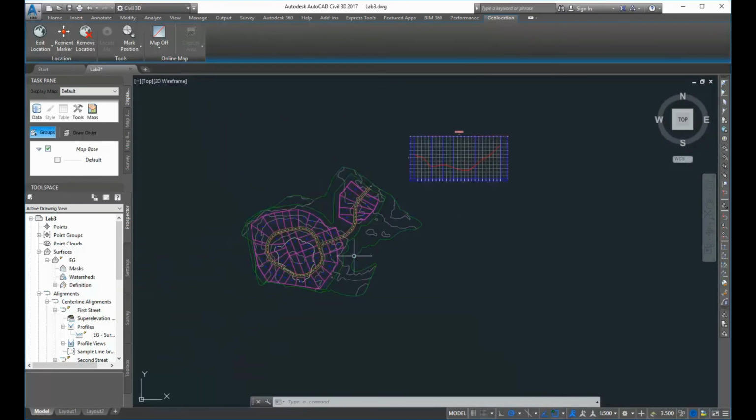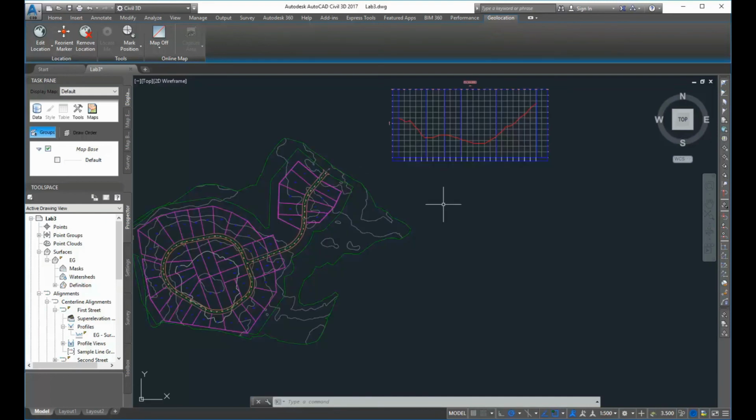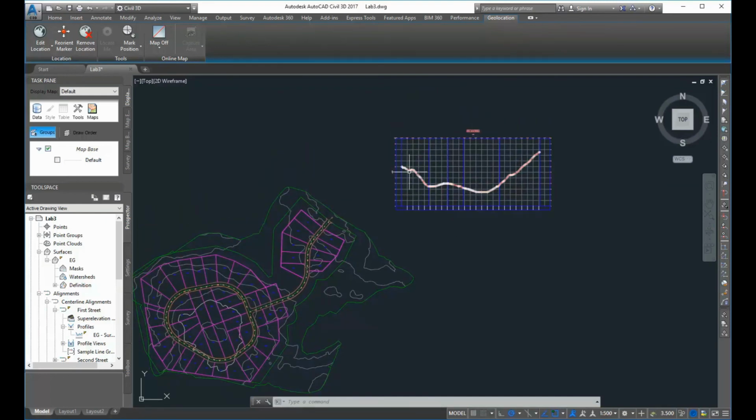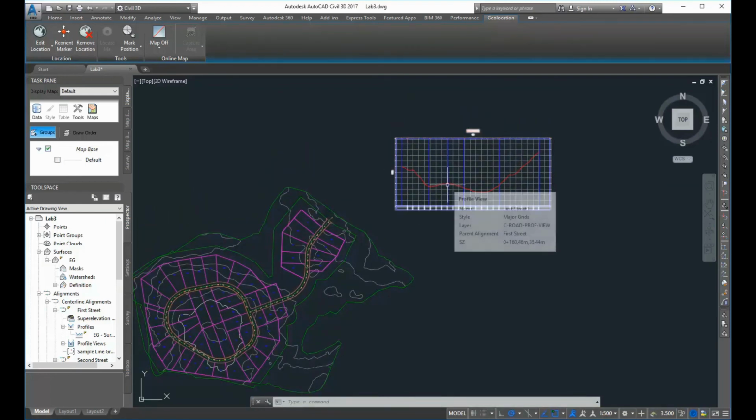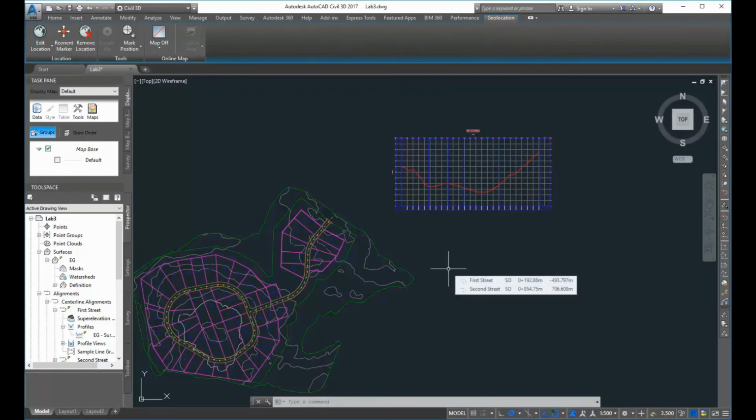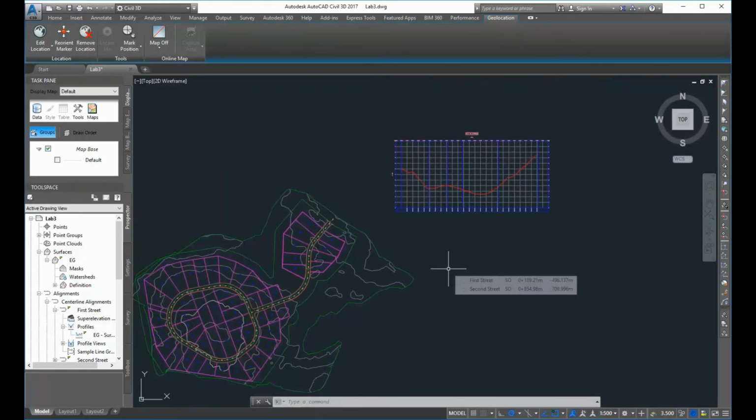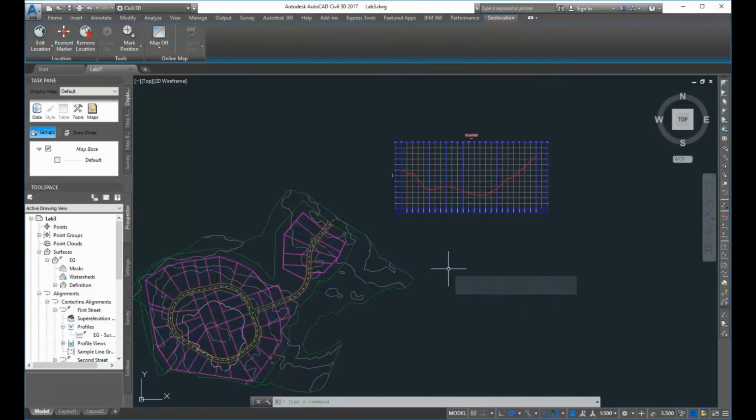For your own project, you would have defined the north and south alignment, and you would have had two existing ground profiles. So for this lab, we're going to learn how to do our proposed ground. Instead of following the topography exactly, we're going to create smooth vertical curved surfaces and do our proposed alignment, and then take it even further and think about the third dimension, which is the cross-sectional element, and into developing what the earthwork estimates are.